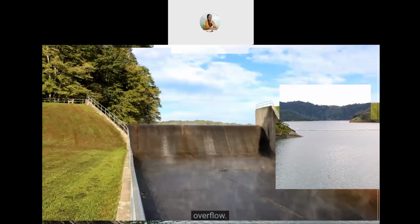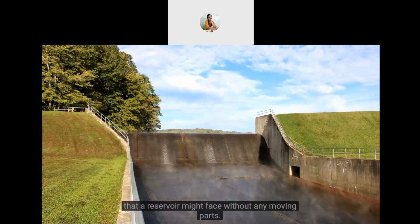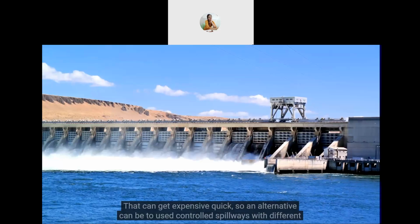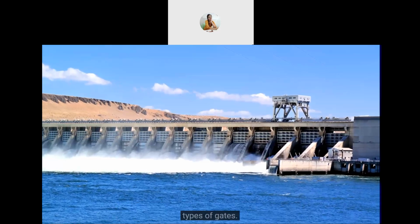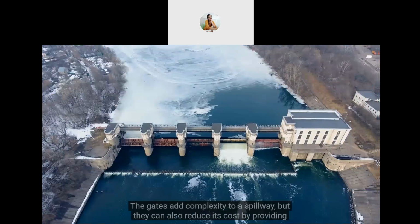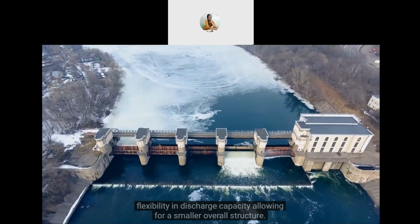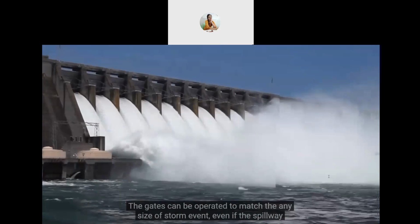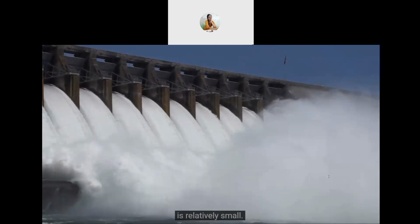Uncontrolled spillways normally need to be pretty big to handle even the largest storms that a reservoir might face without any moving parts. That can get expensive quick, so an alternative can be to use controlled spillways with different types of gates. The gates add complexity to a spillway, but they can also reduce its cost by providing flexibility and discharge capacity, allowing for a smaller overall structure. The gates can be operated to match the size of any storm event, even if the spillway is relatively small.